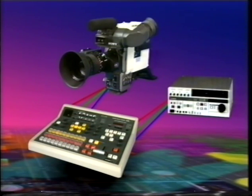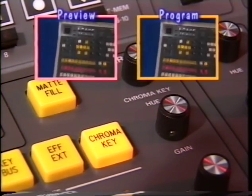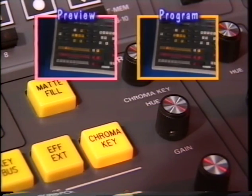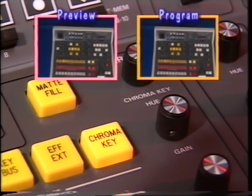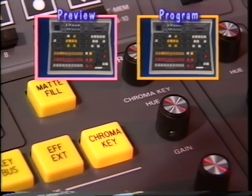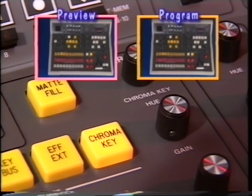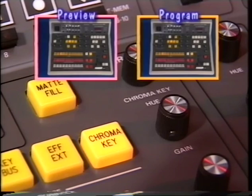The Model 110 chroma keyer will accept either RGB or Y, R-Y, B-Y component video as a keying source. Let's create a chroma key using an RGB camera signal. Place an object or person free of blue or green in the foreground of a solid blue or green-backed chroma key set. Other colors can be used for the backing, but blue or green is suggested because these colors work best when people are part of the chroma key scene.